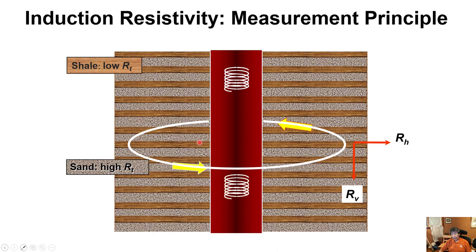borehole induction resistivity tools measure the electrical resistivity parallel to bedding plane, but the new ones also measure the electrical resistivity perpendicular to bedding plane. And there are two directions. Actually, there are triaxial resistivity tools, because in some other contexts, especially when these formations are dipping at an angle, you need the three directions of the resistivity measurement. So we have induction coils in precisely the three directions: transmitters in the three directions and receivers in the three directions. With that, you have a complete set of measurements for induction resistivity that sense the directional properties of resistivity